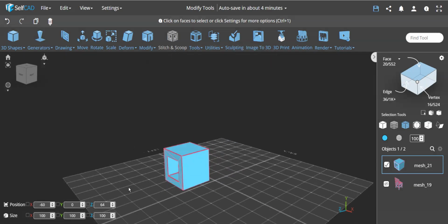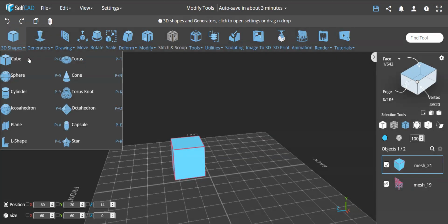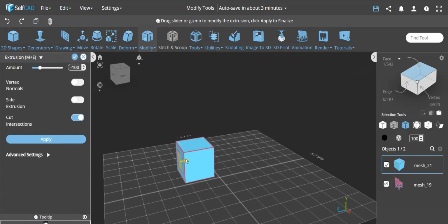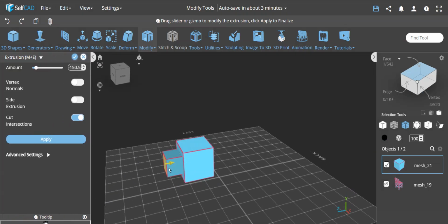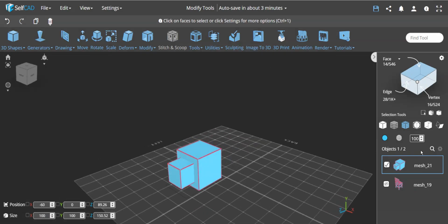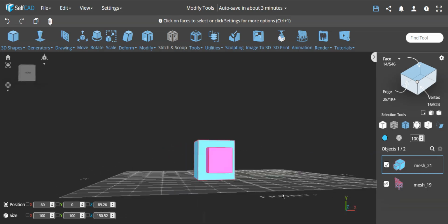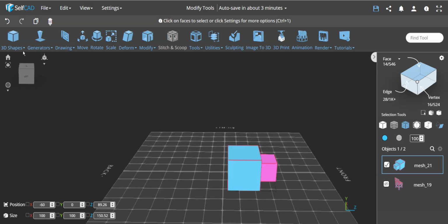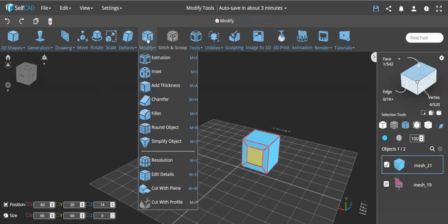If you stick it out the other side, like invert it from the inside out, this actually would not work. This will make it non-manifold. You cannot extrude to come out completely more than 100. If you do something like this, this means this object is not manifold. If I turn on, for example, my back face coloring, you'll see actually this is inside out. This face over here has been inverted and flipped, and this is not manifold. But as long as you do it completely 100, just the exact value, this will create a cut.